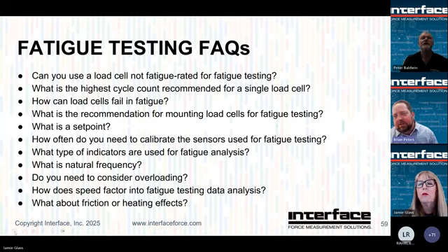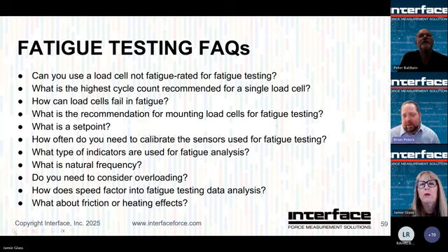If you're using a fatigue-rated load cell, and you have super high confidence it's not seeing any extraneous loads, then yes, it should be good for many, many millions of cycles. But calibration interval is more a confidence factor and an ability to document that there's been no change. If you can do a test and get it done within a year, that's a long test. I would still recommend doing a pre and post cal. If you've got a couple of those that look good, high confidence, then you can maybe extend that interval. So if I understood the question right.